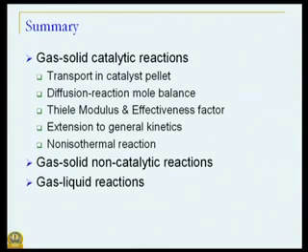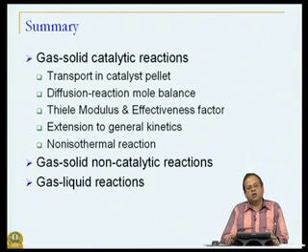Here in gas liquid reaction, one also can talk about rating these diffusion processes and comparing the reaction that we observe with the reaction that would have been there if the diffusion process was not limiting. But a more convenient and practical way of looking at gas liquid reactions is looking at the enhancement factors.